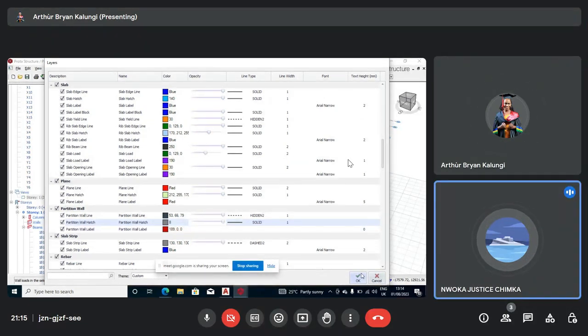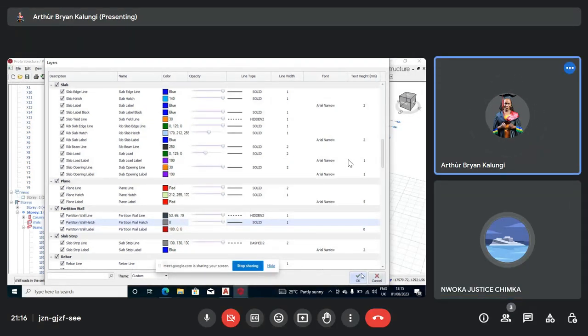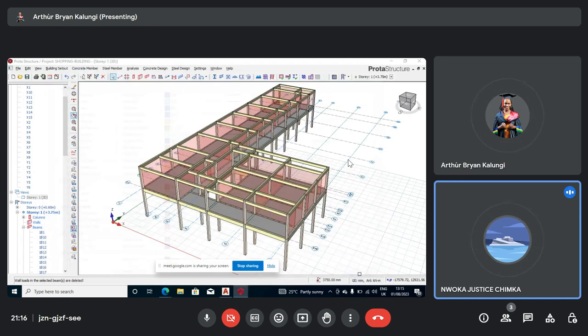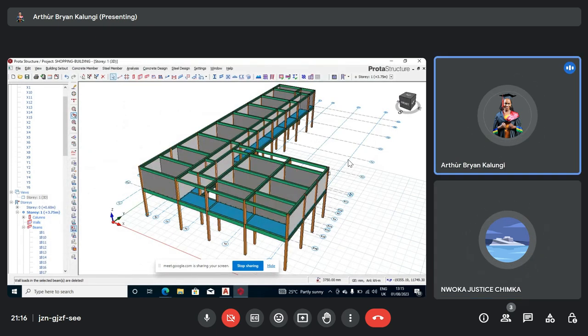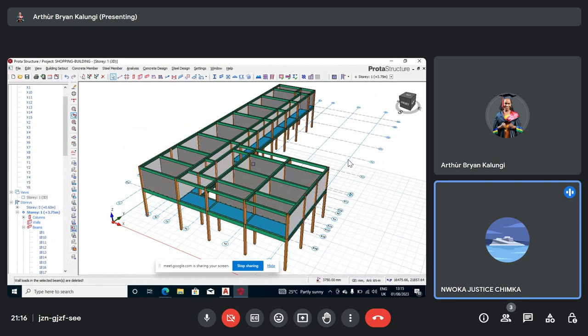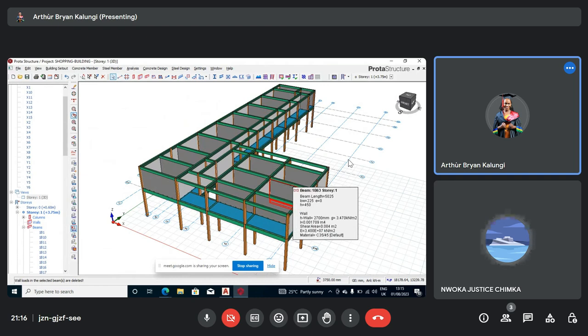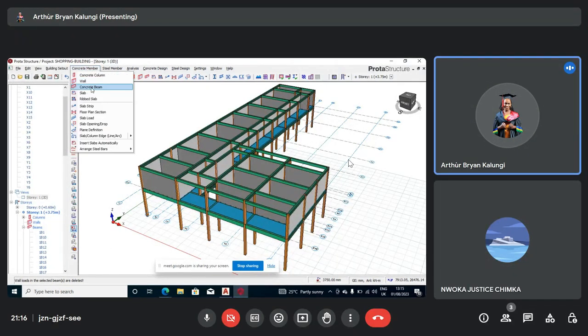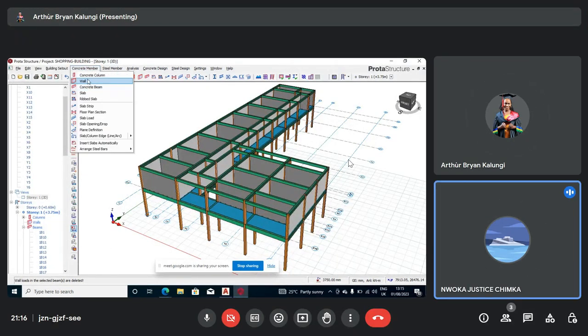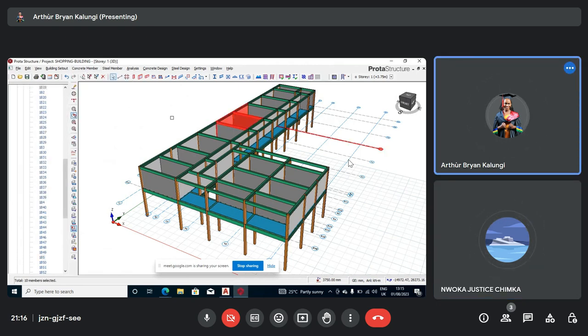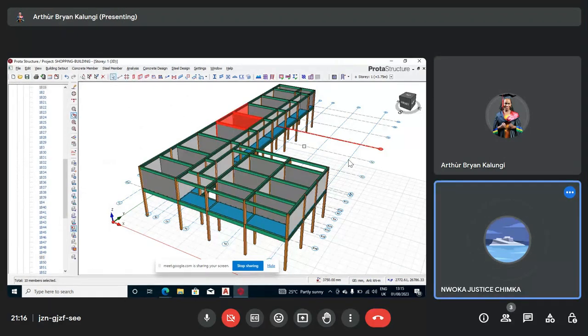No, you don't have shear wall here. Shear wall is for a reinforced wall. We don't have reinforced wall. What we have is just the partition wall, which is the block wall. Shear wall is for lift, like for a reinforced wall, and on this building, we don't have shear wall. Those are block walls. We use that only when we are doing for lift or when our building has a shear wall. Okay, so you can now see how to change color, right?